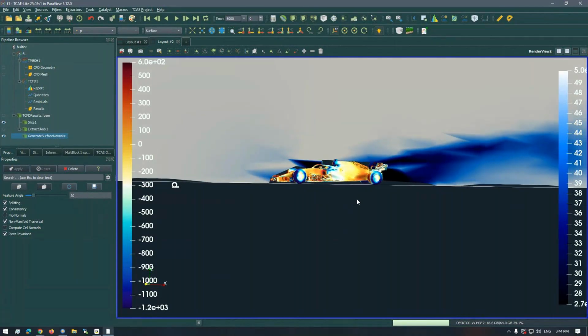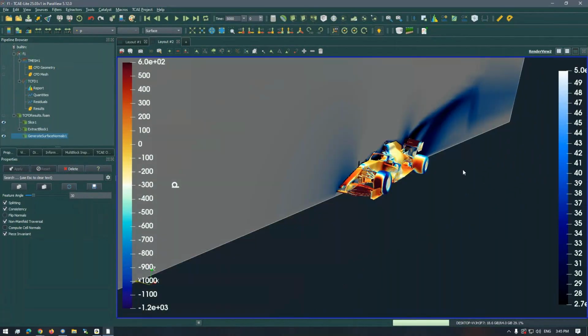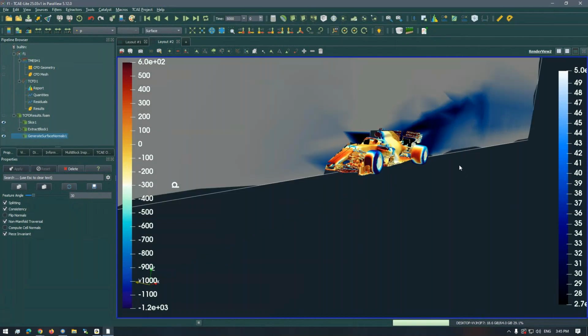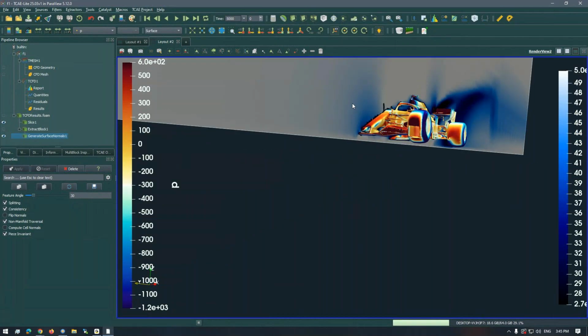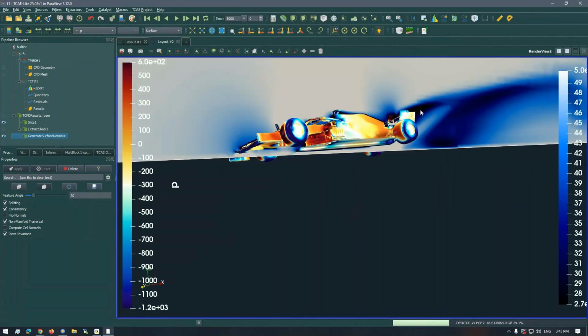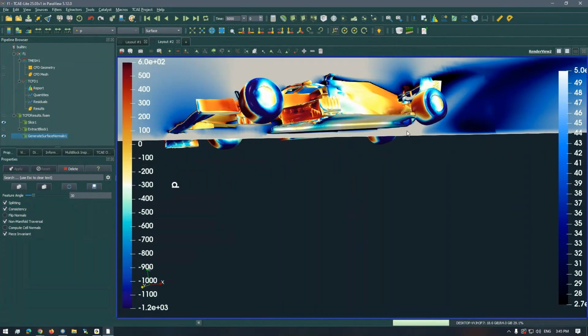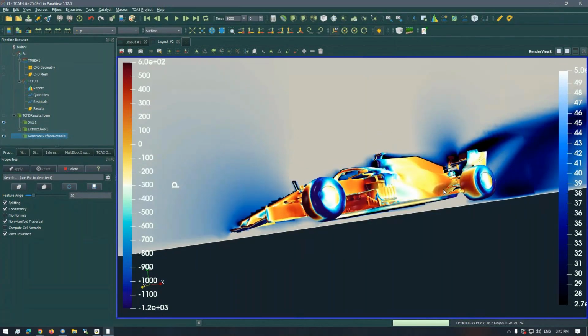There are so many unknowns and parameters that can influence the results that you need to go from the most important one, so the general values. And if you would like to achieve an accuracy of less than 1% with the measurement, then you need to check all the details, including the mesh quality, local mesh refinement, numerics, etc.